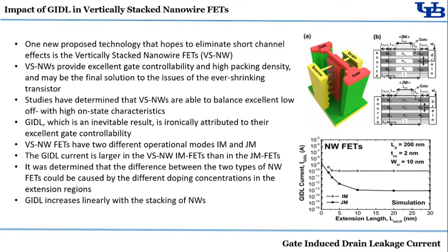The impact of GIDL in vertically stacked nanowire FETs. One new proposed technology that hopes to eliminate short channel effects is the vertically stacked nanowire FETs, VSNW for short. VSNWs provide excellent gate controllability and high packing density and may be the final solution to the issues of the ever-shrinking transistor. Studies have determined that VSNWs are able to balance excellent low off-state with high on-state characteristics. GIDL, which is an inevitable result, is ironically attributed to their excellent gate controllability.